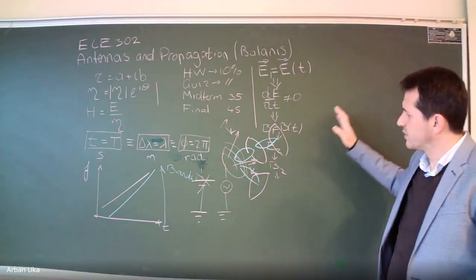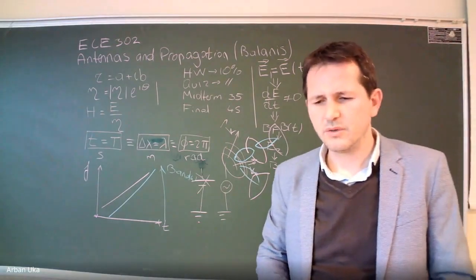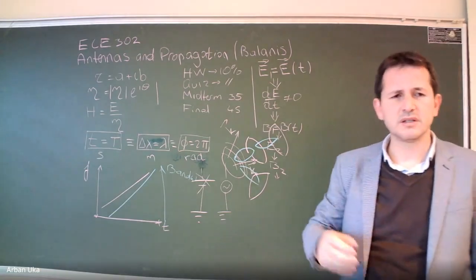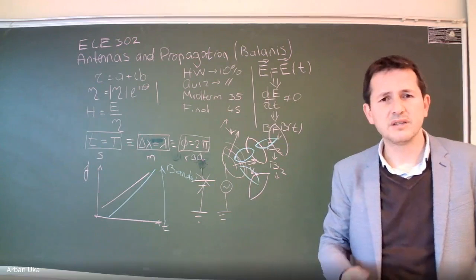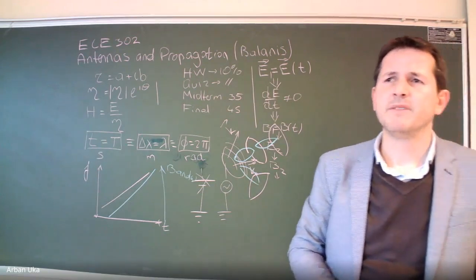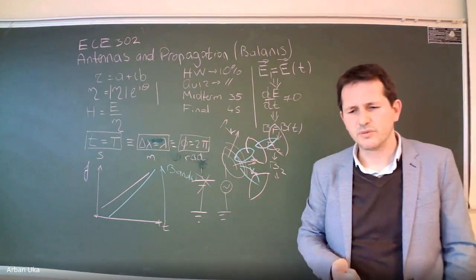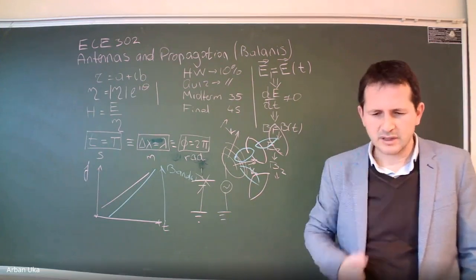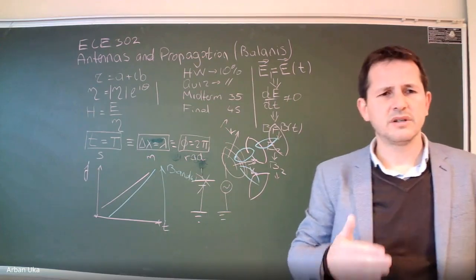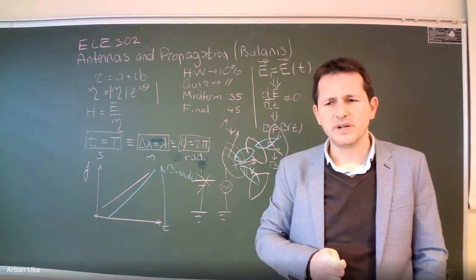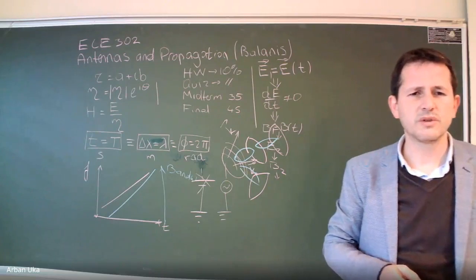And we have a specific performance of how well the waves distribute, how well the signal, and how strong the signal can be at a certain distance, and how much the signal might attenuate because of the properties of a medium. And you know from the electromagnetic waves course that you have taken that waves have a certain length of propagation, where the most critical aspect is, for example, a parameter which we used to call the skin depth.